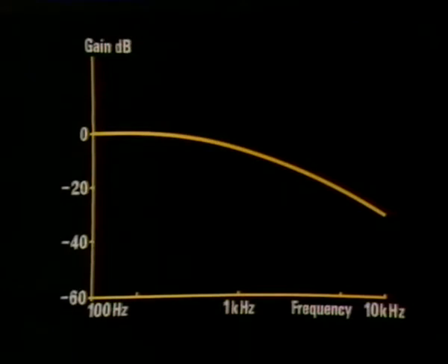Of course, Mike was talking about acoustic filters, but you're probably more familiar with electronic filters. These allow some frequencies to pass through and they suppress others. The RC circuit in your home experiment kit is a good example. The amplitude response of an RC filter can be drawn as a Bode plot like this. Remember that the vertical scale is logarithmic, measured in decibels.